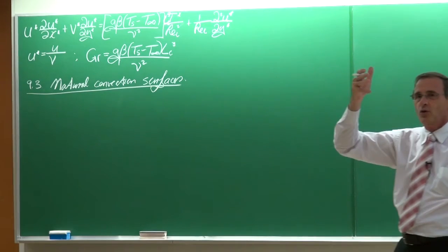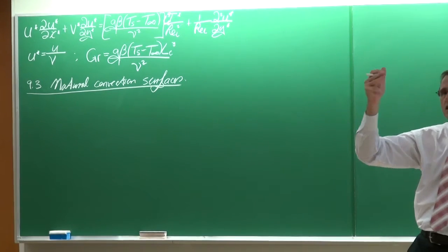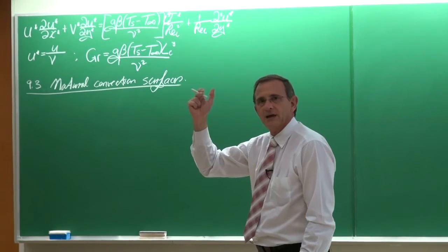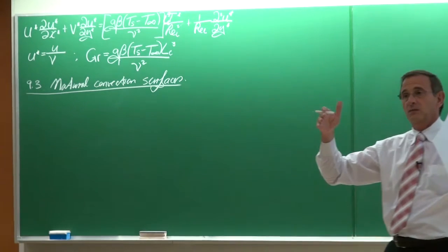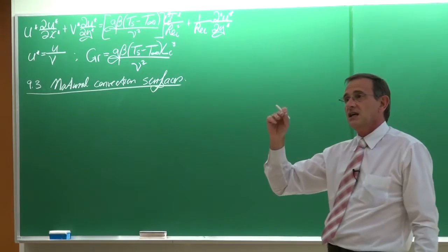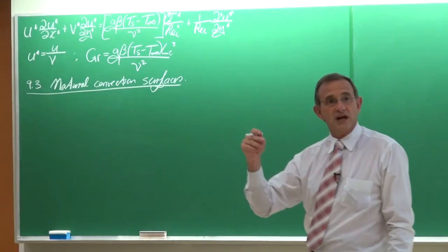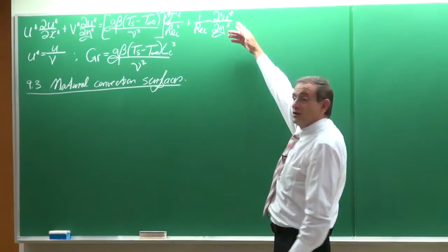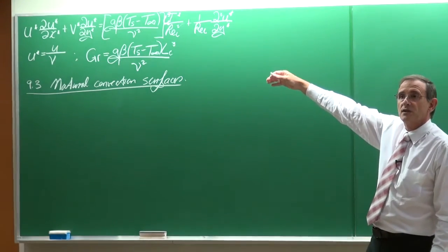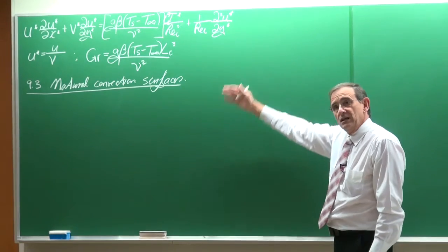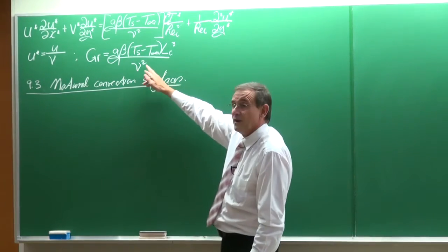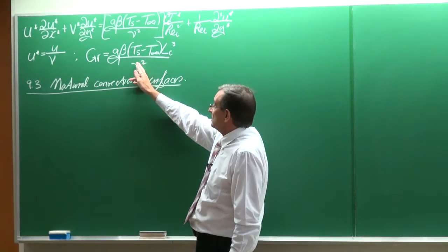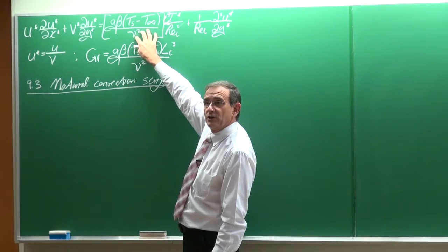Now, it was all about the fact that there are three equations: the equation of mass, momentum, and energy. And you've derived them in Chapter 6. But in Chapter 6, the specific assumption was made that there are no buoyancy forces. So the only equation that had to be changed was the momentum equation. And in the momentum equation, where this Grashof number actually comes out of, this is not the new momentum equation. This is just a term in the momentum equation.